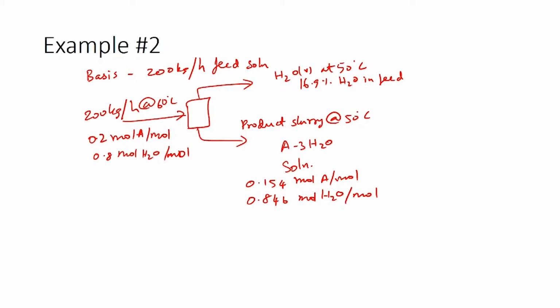So, let us first label this flow chart and identify the parameters which need to be calculated. We have mass flow rate, however, we need molar flow rate because all the compositions are given in terms of mole fractions or mole percentages. Let us call this N0 dot kilomoles per hour of feed which is coming in, and we will call N1 dot kilomoles of water per hour which is water vapor leaving the system.